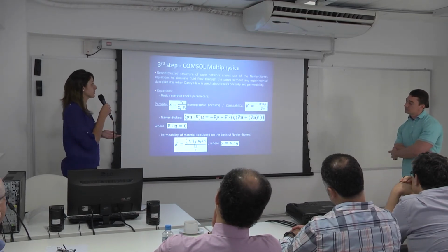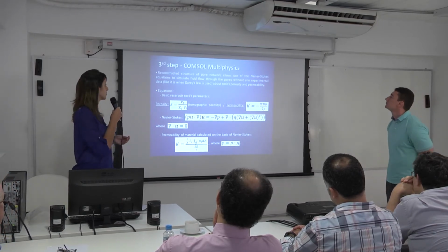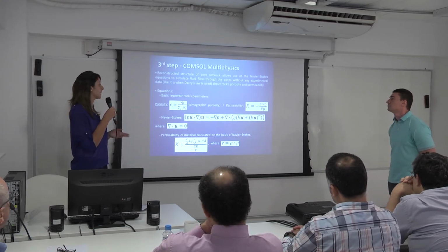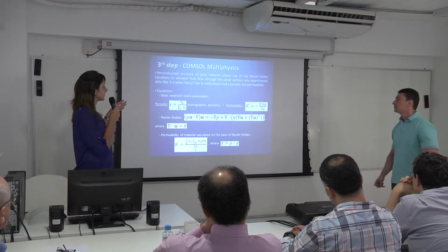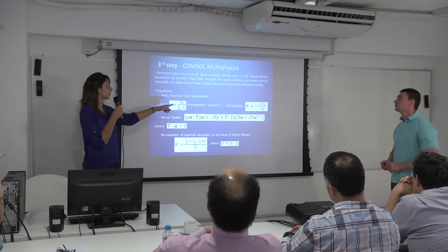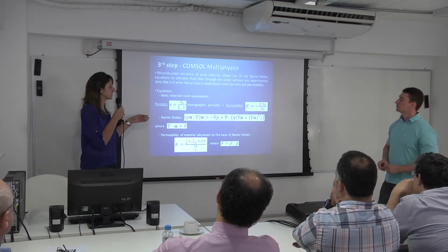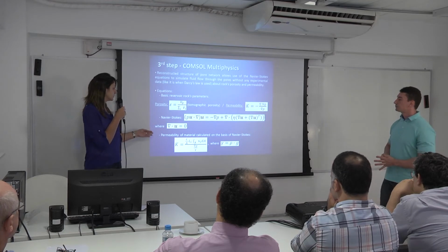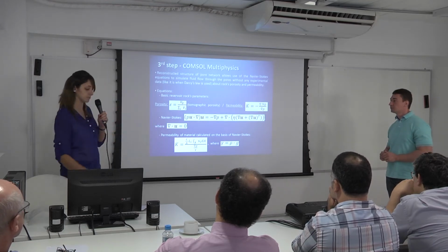Reconstructing the structure of the pore network allows use of the Navier-Stokes equation to simulate fluid flow through the pores without any experimental data, like we have to do with Darcy's law. So the equations used in Comsol are going to be the porosity, that we are going to calculate from the tomography, the Navier-Stokes simplified, because we are going to use this stationary model, and the permeability calculated from the Navier-Stokes equation. That's going to be this one.